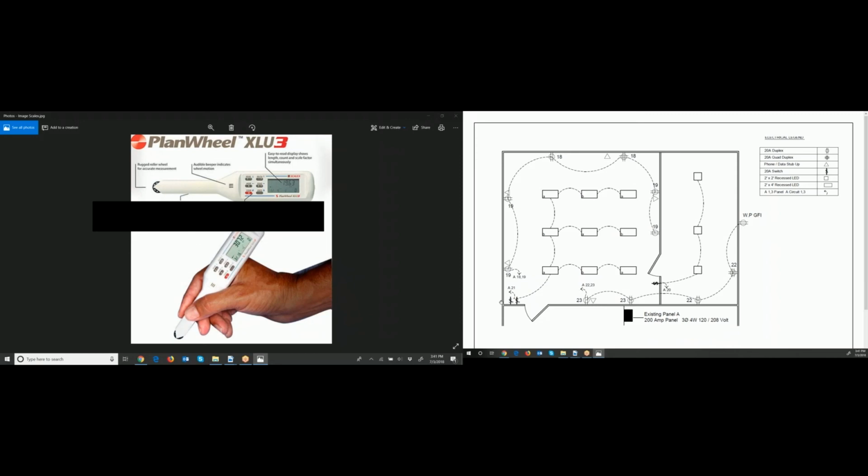Now, another thing I want to explain, when you're taking off conduit, always take off at right angles to the drawing. So in this case, what I would do is, as I explained, roll down below that till I got several feet to allow for the riser, and then I'd put my cursor or roller, my scale X, on here. I'd roll over and up, straight up, again at right angles. Okay, so that's it for the rolling or how to take off conduit.